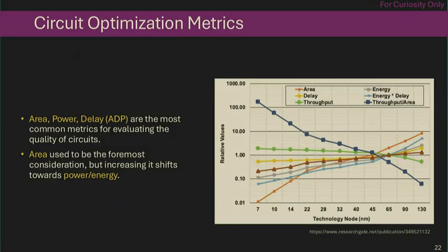And that raises the question of what people call dark silicon. When silicon, like semiconductor chips, are running nowadays, some of it is having a very high power density, is doing all the work. The other half is probably just idling and not doing much. So you get this imbalance in power density across the chip. And overall, your power density is also much higher than 20 years ago. And that raises all the cooling issues. So nowadays, power could even be the #1 design consideration.